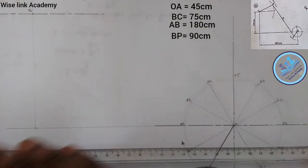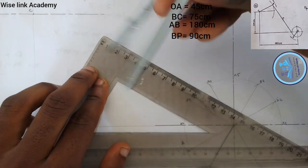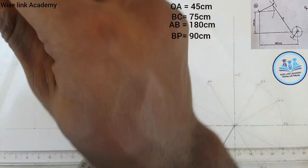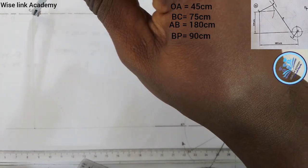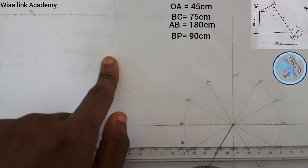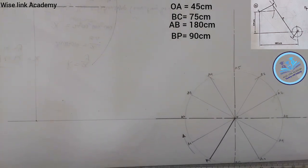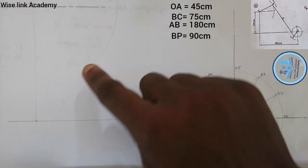And the distance AB is 75. I will measure my 75 from this point here to this point. This is my 75. Then I'll place it at this center point here, as you can see, and I will strike an arc this way. So this arc I've struck will help us locate my point B. So next up, this is my arc of point B.